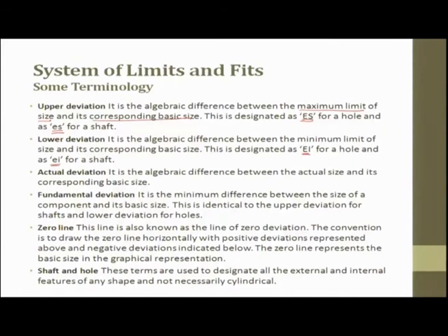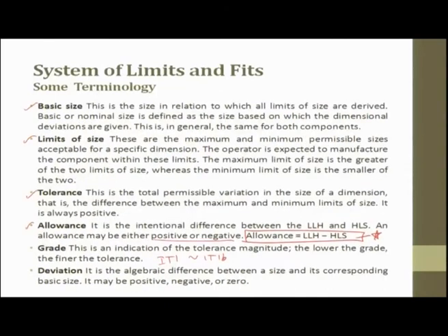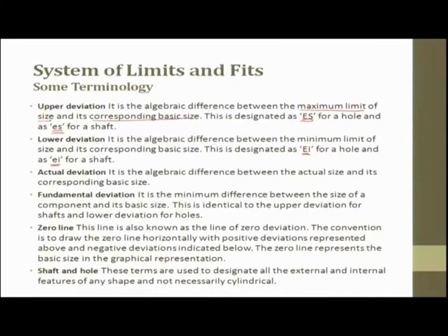These are the deviations. So, please try to understand deviation. It is the algebraic difference between a size and its corresponding basic size. So, upper, lower. What is actual deviation? It is the algebraic difference between the actual size and its corresponding basic size.